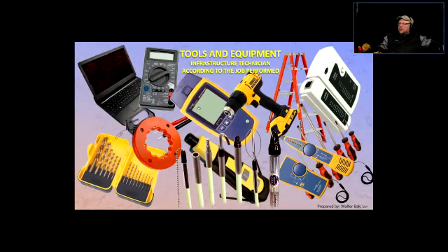The qualifier, and also I haven't listed, is something that's called a certifier. The qualifier is the one that we used a lot in our class during our labs. This will check for the wire map when it comes to data cable. It will check the wire mapping to see if all the connections are made. It is going to check for the length, if it's not too long, because if it's longer than 328 feet,